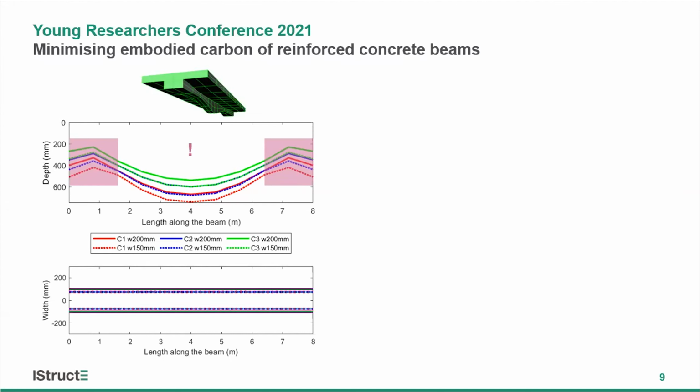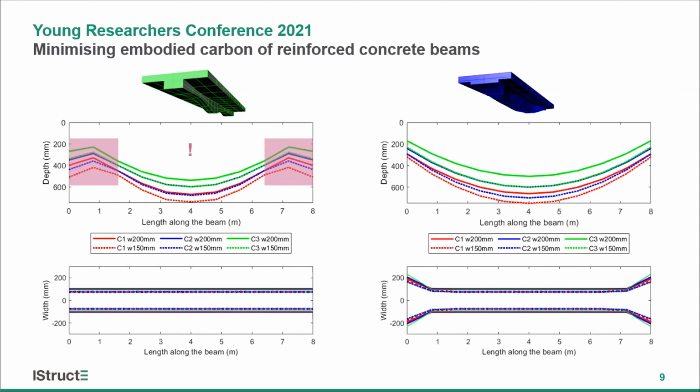This is not only challenging in terms of supplying the reinforcement in practical terms, even if we supply the reinforcement somehow, when the reinforcement is in tension, there will be an increased shear demand. That is why we have to talk about feasible optimum shape finding. There also, as you can see, the optimum shape has depended on the design load case, and it has depended on how thin the beam can go.